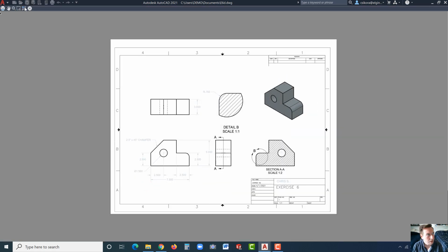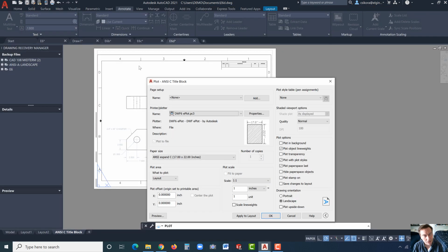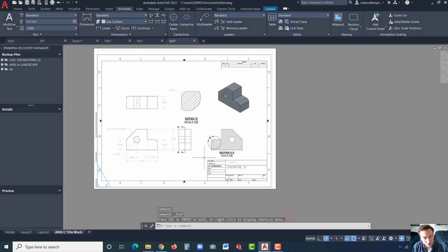All right. Now, you could output it as a PDF. And what's nice, rather than trying to scale it down in here, once you put it in a PDF, even if it's a C-size drawing, you could actually print it from the PDF and tell it to scale a little bit easier sometimes than all this multitude of options, which there's a reason why there's so many options in here, because plotting is a bit different than printers. There's old pen plotters that had little pens attached to them, and they support all those tools, so you don't always see that. Anyhow, all right, so there you go. You could select the PDF output and do that.